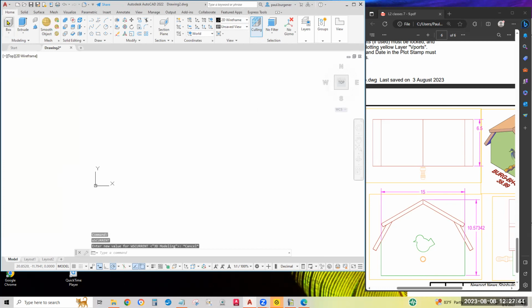I'll just use a box Boolean. I'll click there. I'll pick the length, line up the cursor with the X. I'll say 14 in the X direction, enter. 5, did I say 5.5, in the Y direction? And all boards will be a 1/2 inch, so the height will be 0.5, enter. I think that's right. Let's go to the 3D free orbit.